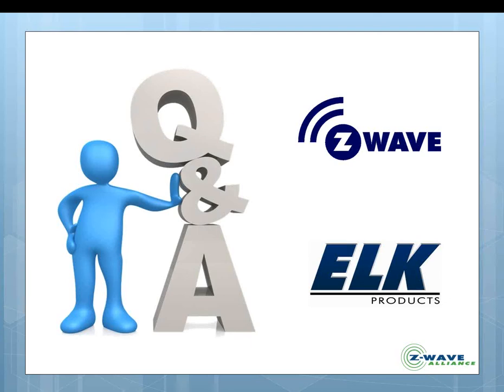One thing that you do need to keep in mind when you make any kind of changes or additions, or maybe you've removed some devices for whatever reason, any type of changes that are made to the Z-Wave network, to make sure that the M1 is aware of those changes, you do need to go back through that checklist of making sure that the controller is updated, that you've gone through that RS-232 setup step so that the controller has all of that information in the format that the M1 needs.